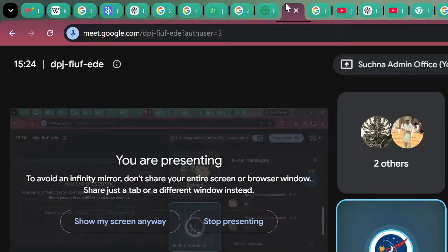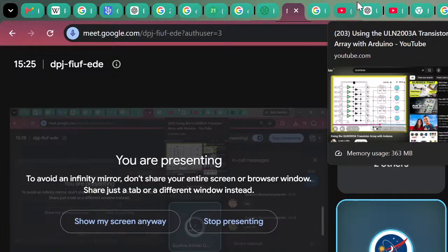Yeah, it is used to control a high voltage application with a low voltage, but both are independent with each other, both are not connected. So how is it working? With the help of magnetism. Whenever you apply an electric current, a magnetic field is produced around the coil. Due to this magnetic field, the armature moves and attracts the contacts, and therefore it forms a conductive path for the higher voltage. That's how you are conducting. That's the working mechanism of a relay. Similarly, the principle is different for an optocoupler or optoisolator, which we will discuss. You actually missed that.